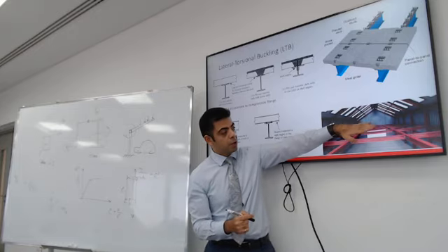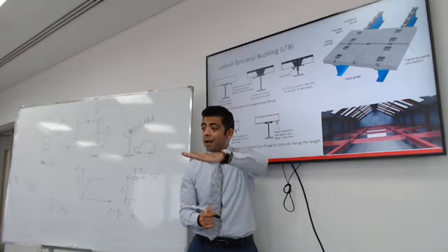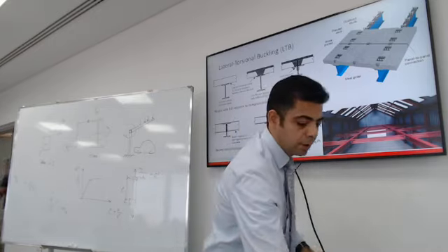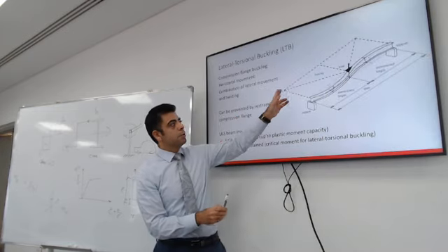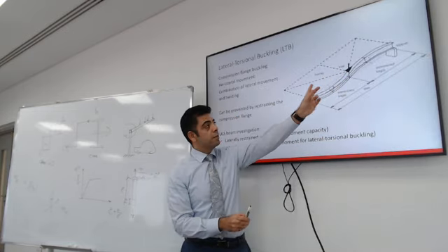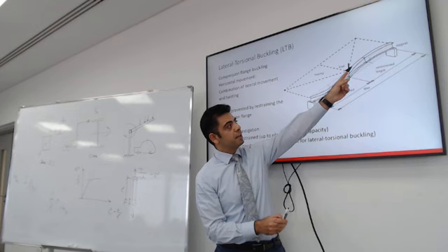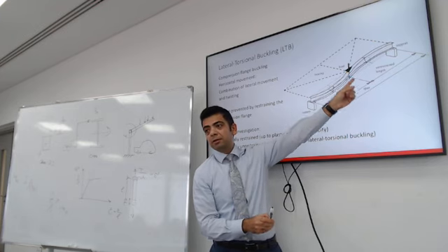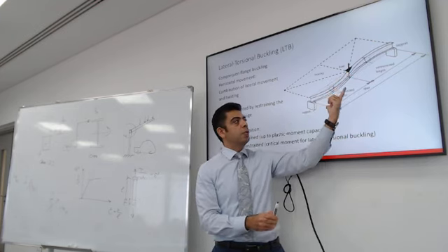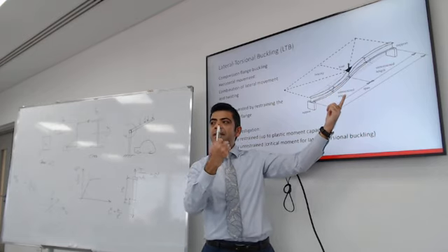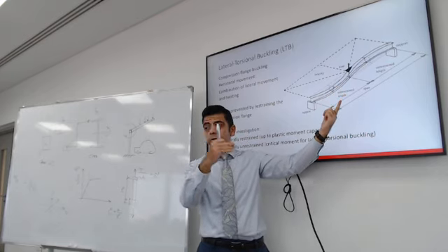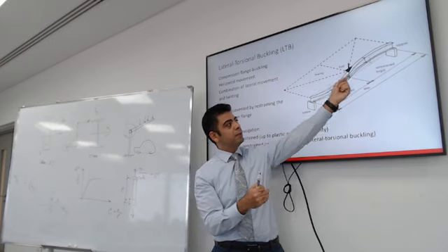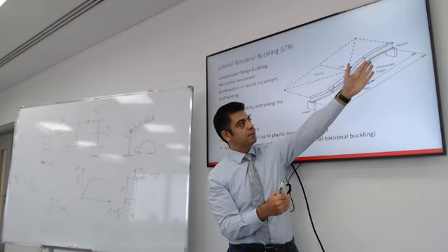Yes, that's a good question. You can do a truss in the lateral direction. So it would look something like that. Do you see that truss? Yes. That truss here is preventing this point from moving laterally. So the only span that needs to be designed for lateral torsion buckling is the distance between the braced points.